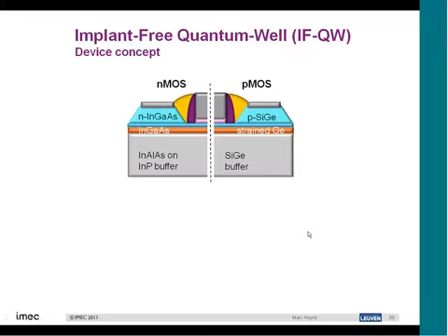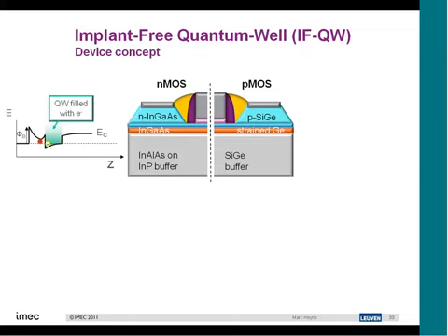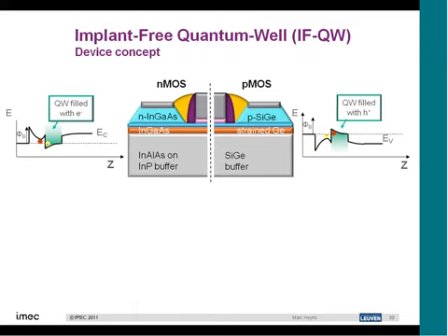And obviously, I think you're not going to do all the effort to go to III-V materials where you can have all this beautiful bandgap engineering just to make a standard inversion mode device. Actually, you want to use this bandgap engineering to make quantum well devices, because they give you the advantage of much better electrostatic control and much higher carrier mobility. So these are the kind of structures that we propose.